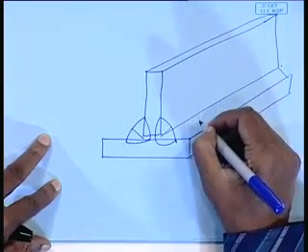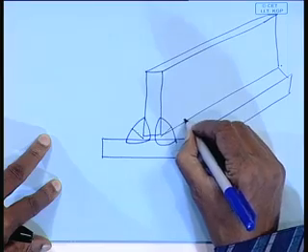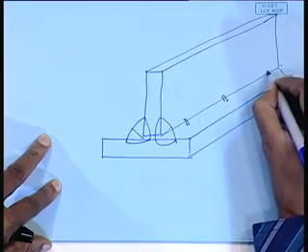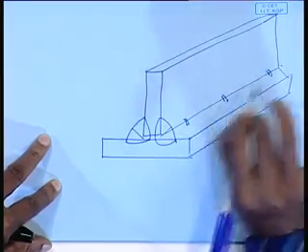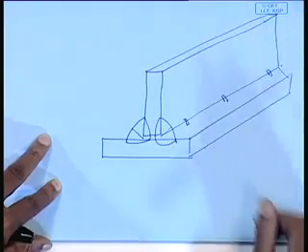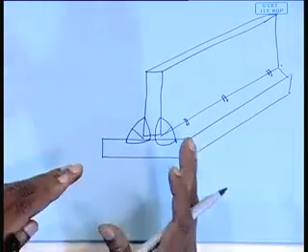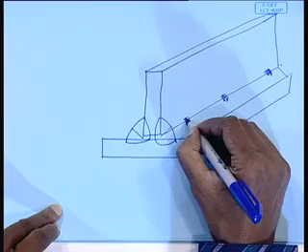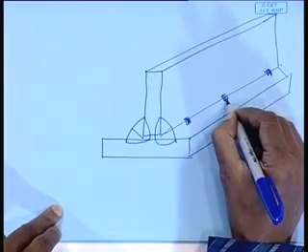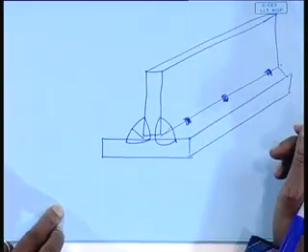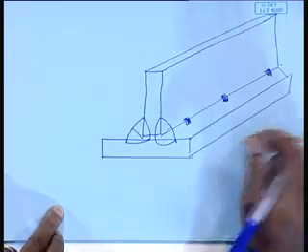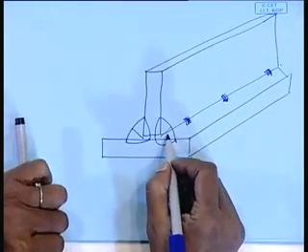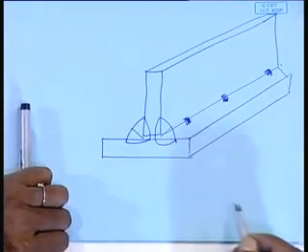Next, before welding, we did some tacking at small intervals, small tack welds, and then welded, and there was no crack. That means the stress redistribution taking place, because of the tack welds, the stresses developing are totally different, or the extent of tensile loading coming on the fillet is not cracking it.